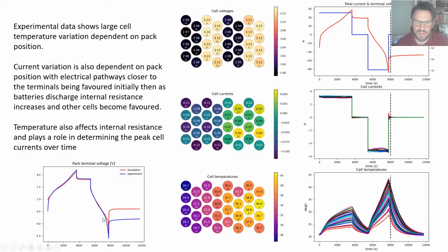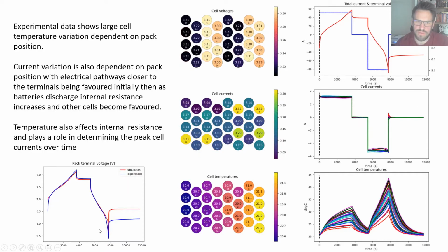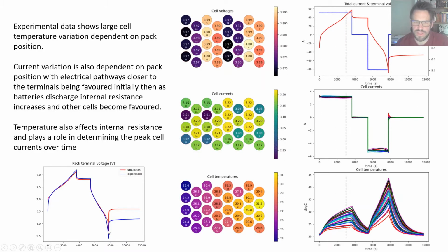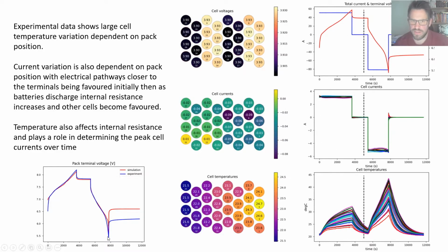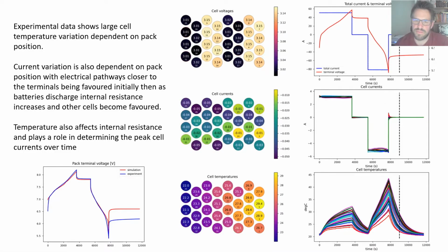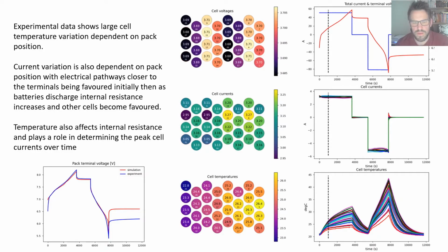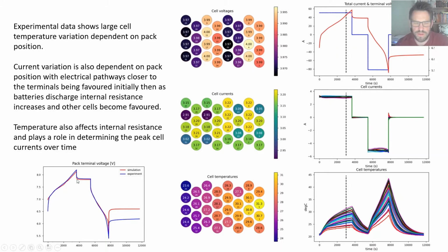It's actually because it's at the end of the voltage, sort of the end of the minimum voltage range. There's quite a steep drop off there at the end. So any slight variation or uncertainty in state of charge is actually going to manifest in quite a big voltage difference. But we seem to be getting a really good match for the rest of it.